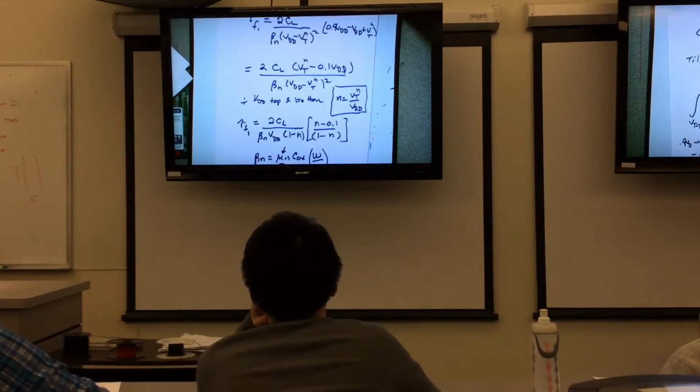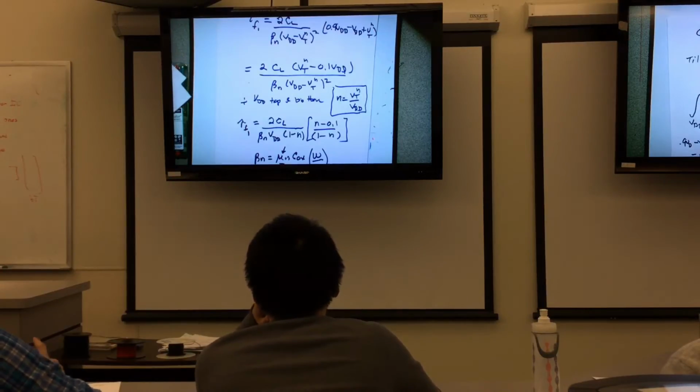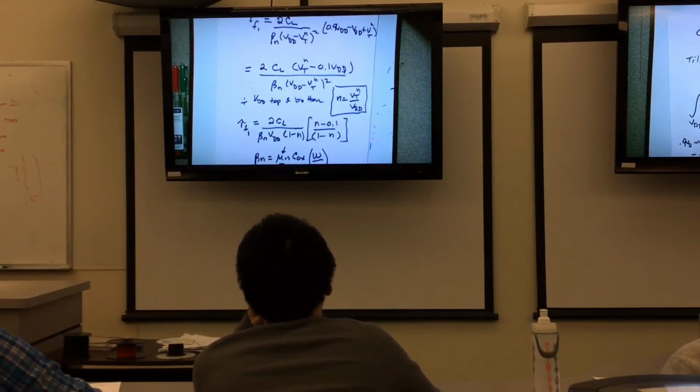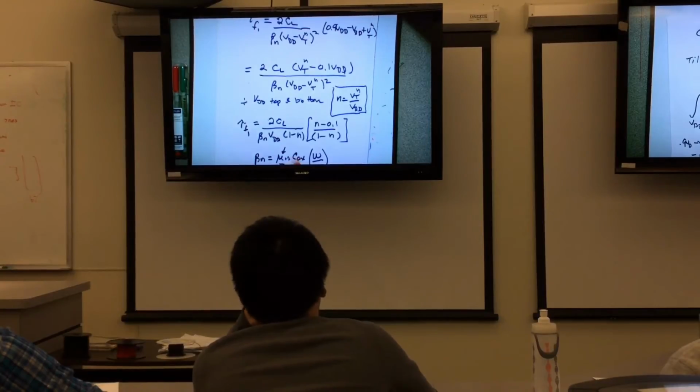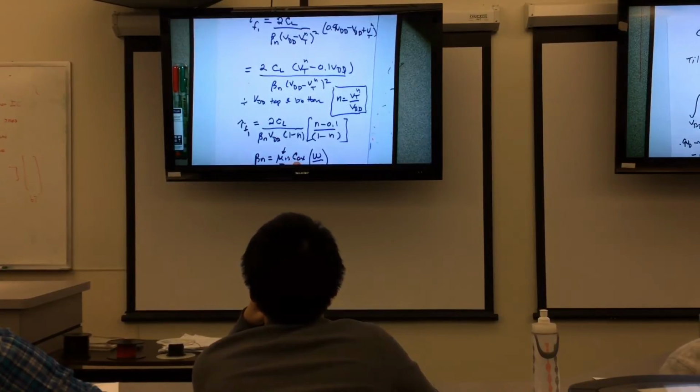And this is common even for the Josephson junction technology. But you've got to have this enormous uniformity. Very hard to do for anything other than silicon dioxide. But they did find something. It was silicon hafnium oxynitride, which had maybe a dielectric constant 2 or 3 times larger than silicon dioxide. So this could be made bigger without having to shrink the thickness of the device. And so that would help with the charging and discharging mechanism.